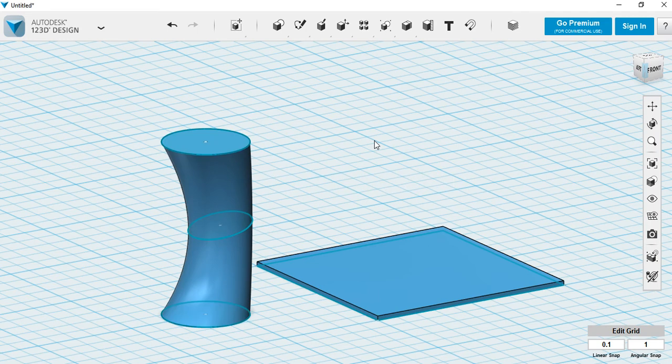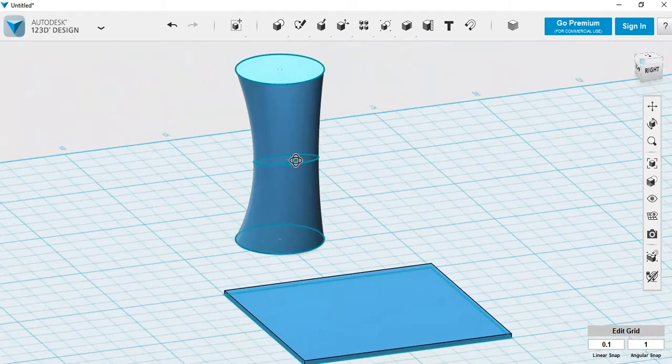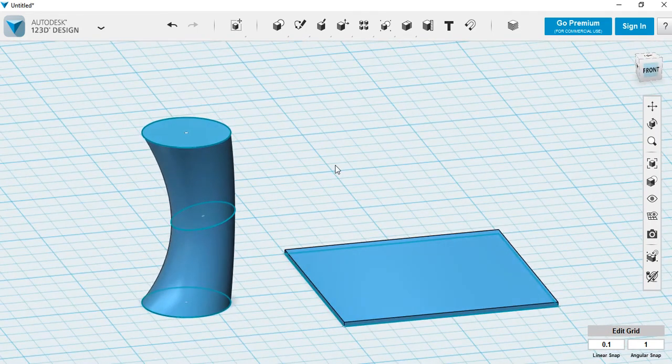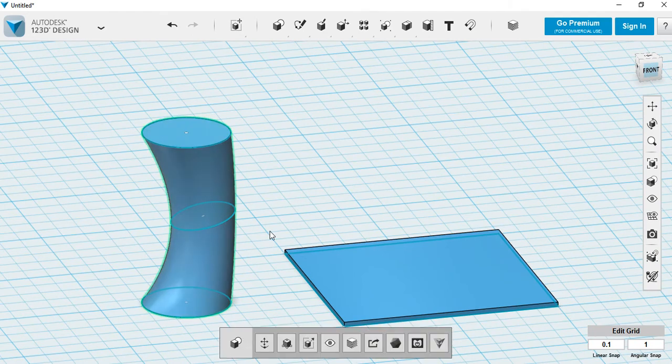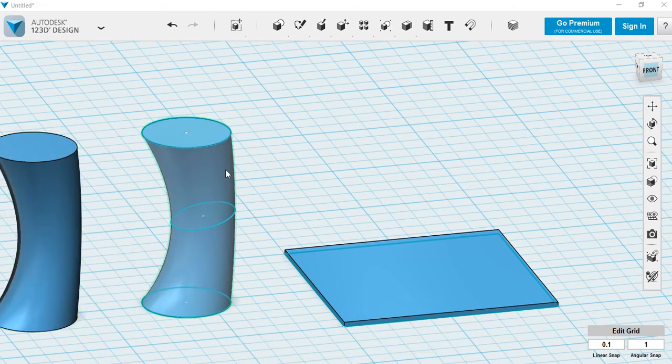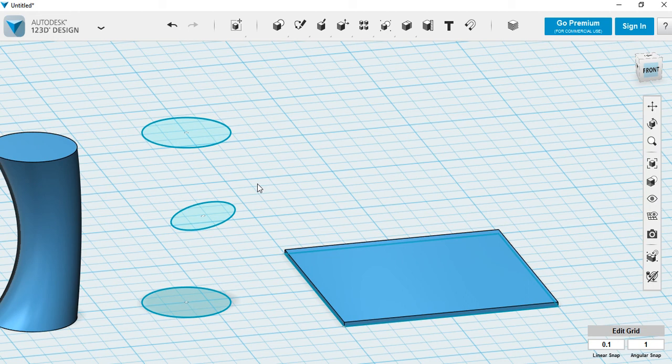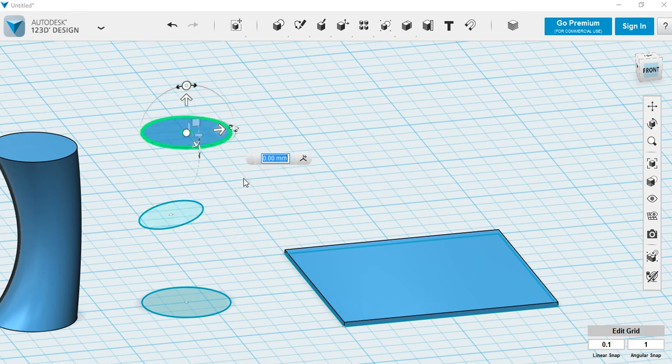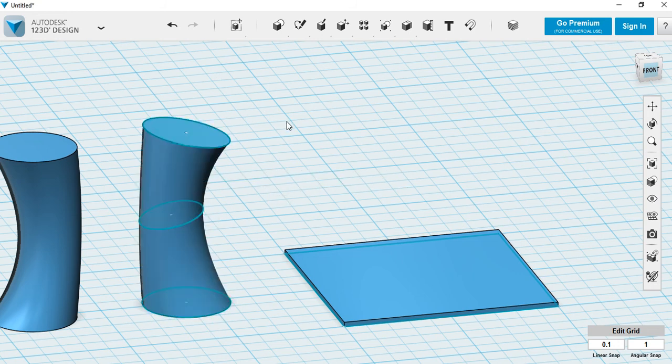And then I'm going to select loft. And then the loft is created. Have a look at that. See if that's what you intended. If it's not, then you can always select the shape just in case you need it, copy and paste it, move it to one side, delete the shape that's there, and then you could edit the circles or the sketches again, change them, do whatever you need to do, select them again, bottom, middle, top, go to loft, and there we have another shape.